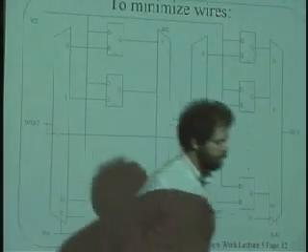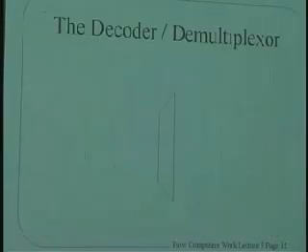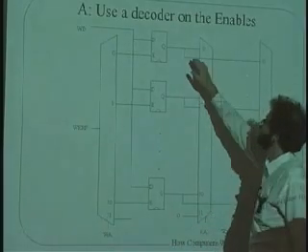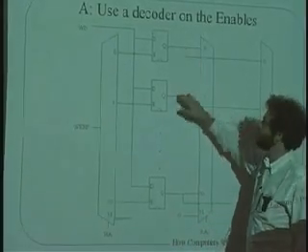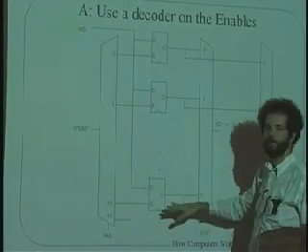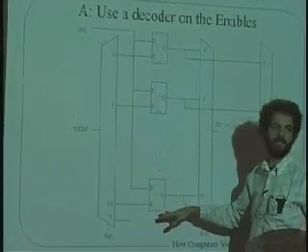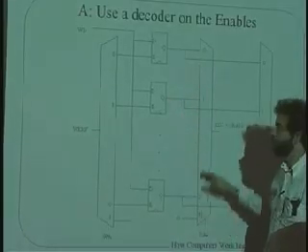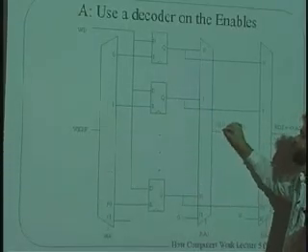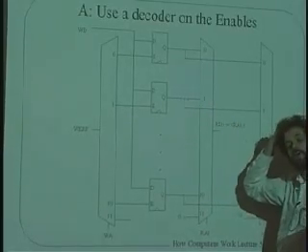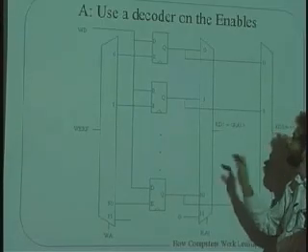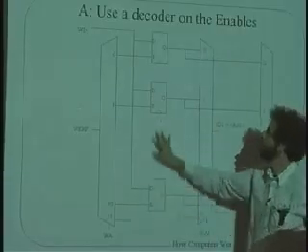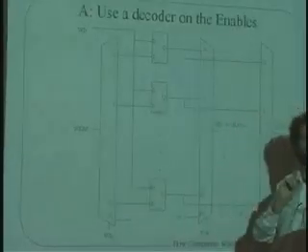Now, in order to grasp why this picture is important, let's back up a second and look at the previous picture. You'll notice in the previous picture, I have 32 bits coming out of each of these registers. 32 plus 32 plus 32 plus 32. I have 31 copies of 32 bits, which is many, many bits. And they go to this multiplexer right here to select one of them, and then the output comes out here. A typical register file back in the 1970s, 1980s was built as a single chip with this multiplexer and the registers all inside of one integrated circuit.